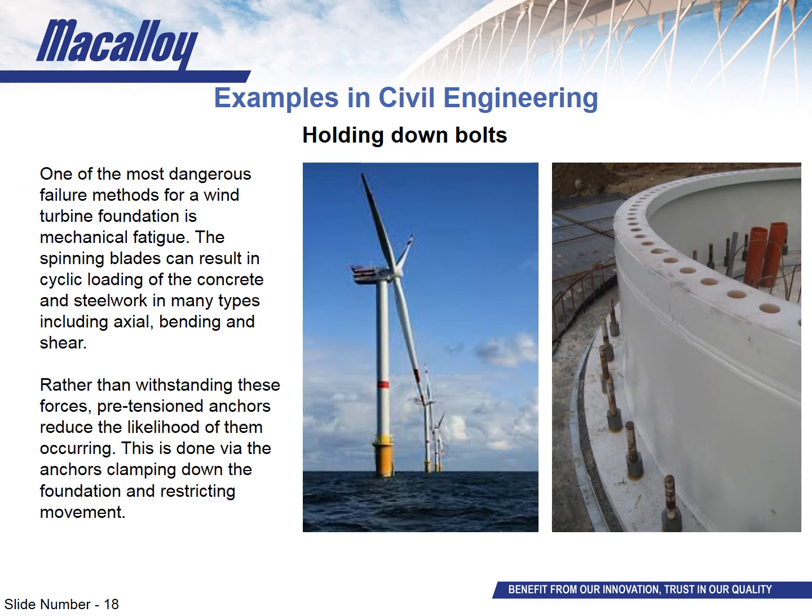As with the last example, preloading the bolts in the foundation actively clamps it down, both minimizing movement and reducing any likelihood that the stress in the bars will significantly change. While beneficial, even preloading cannot completely mitigate fatigue demands, so a tested, fatigue-resistant product is necessary for complete assurance of